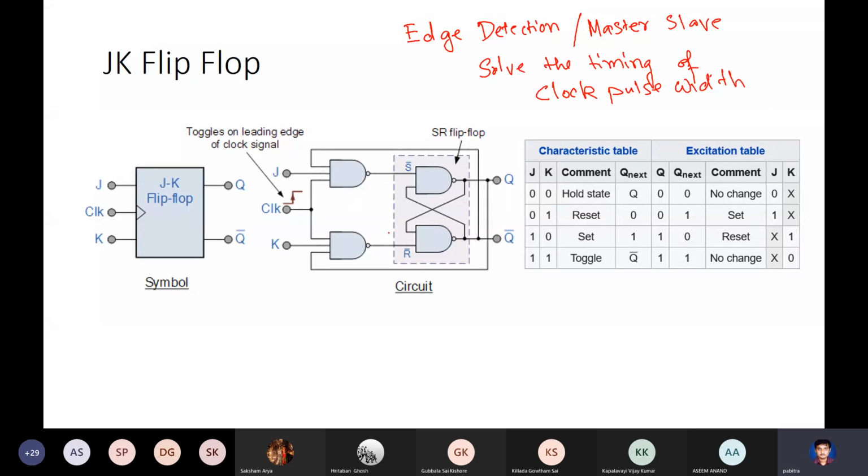Okay. So what I will do is the following. Let's take the flip-flop. By the way, this is the symbol of the flip-flop. This is called a clock. In fact, this is not the clock. This additional wedge is there. I'll tell you what this means. This means that if you look at the timing diagram, this latch is enabled or activated only in the up edge, only in the up edge of the clock.